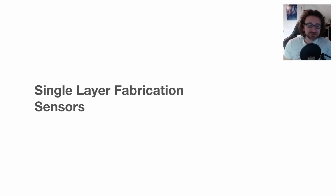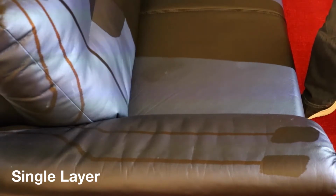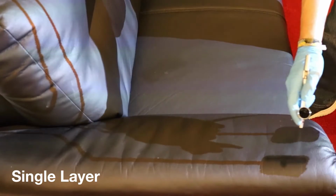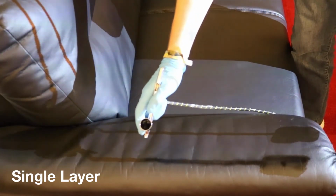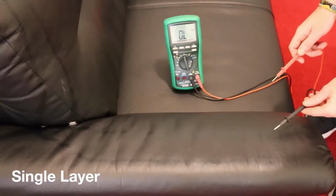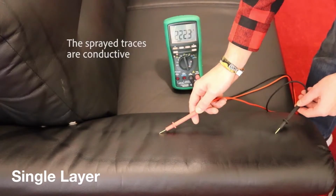Wonderful. Let's first focus on what the single layer fabrication looks like and how we can fabricate sensors with this approach. Here you can see how this can look. We spray here on a soft and curved leather sofa. We have a set of projected stencils, and we use the airbrush to spray a transparent conductive ink directly on the surface of the sofa. We follow the projected stencil, and once we are finished, we have to let it dry. After it is dry, these traces are fully conductive, as you can see in this example, and they can be used for sensing user input.